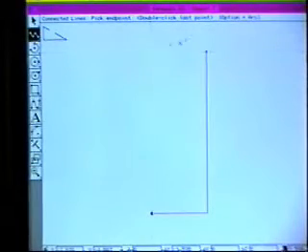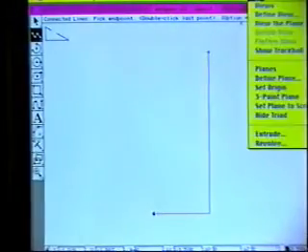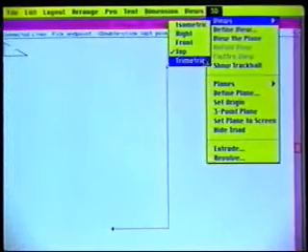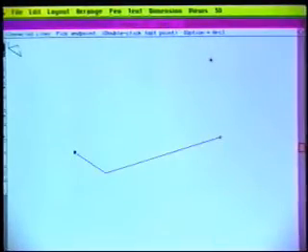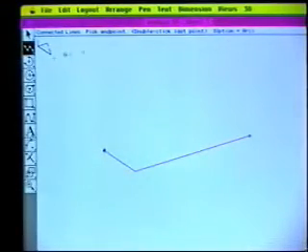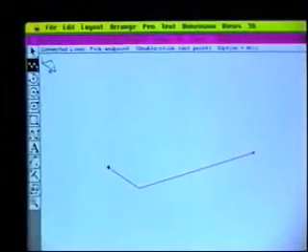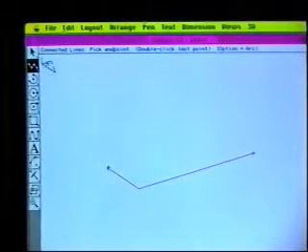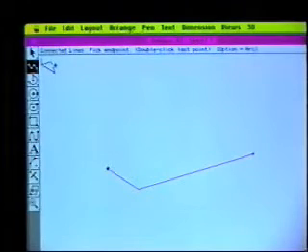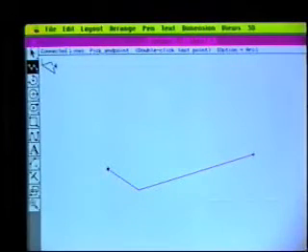But let's do the same process in 3D. I will go to the 3D menu and change my view. Instead of being at top, I will change the view to be trimetric. And you see that the rectangle has laid down, and also notice over here that the triad has changed. Now what this shows, this line here is the x-axis, this line is the y-axis, and this little line is the z-axis. So this is a little reference plane indicator, and the little broken line here indicates the work plane, which is laying flat on the bottom.